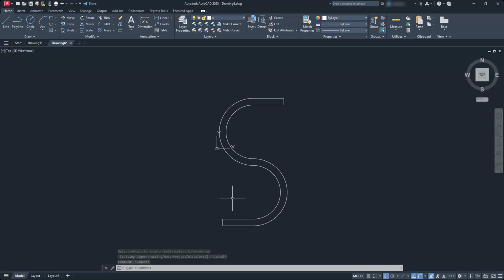Another way that we can do this is also use the rotate command. And I'll show you that as well. Let's go ahead and put the finishing circles on here. I'll just use a 2-point circle. And that's going to allow me to go ahead and click that endpoint to this one. Likewise, we're here at the bottom. So just hit the enter button. Select 2P. And then select that endpoint to this endpoint. And then go ahead and trim off the rest of this, right?